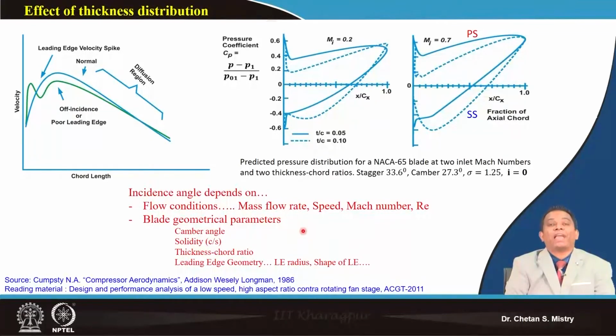Now onwards, the angles we define will be defined based on the blade metal angle, or blade manufacturing angle. The blades we are looking at are designed and fabricated by considering the change of incidence angle. Suppose my air angle is known to me, beta 1 and beta 2, mainly beta 1 is known to me. I will incorporate my incidence angle there, and based on that I will make my blades.